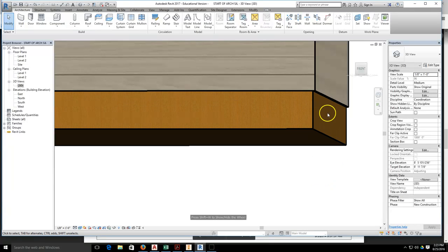After the building is framed, there's an additional piece of sheathing added to the outside of the floor system that then makes the entire house flush with sheeting. So if we needed to add sheeting to flush that, that's when it's needed.